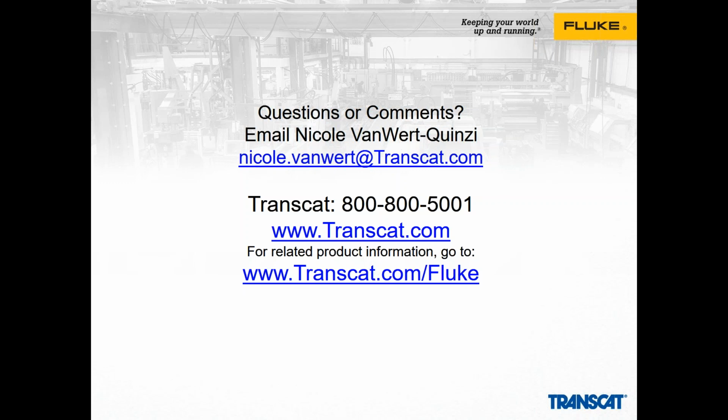Okay. Next question. What causes harmonic distortions? Okay, so the primary cause of harmonic distortion is electronic loads. Now, there's many types of electronic loads. They can be as simple as a switch mode power supply load, but they can also be things like variable frequency drives. There could be UPS systems. It's any electronic load. They will always cause some amount of distortion.